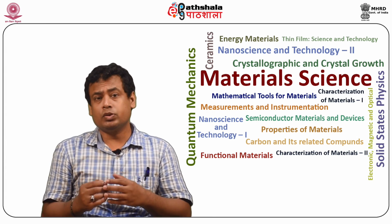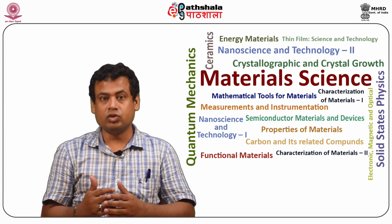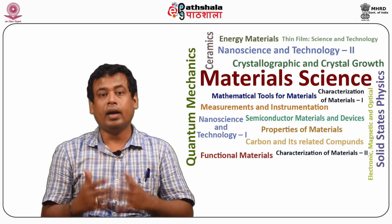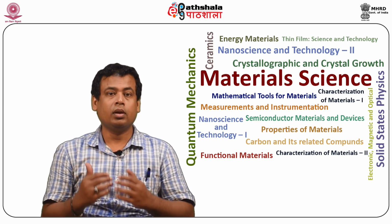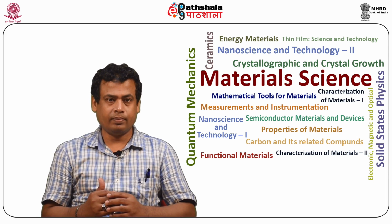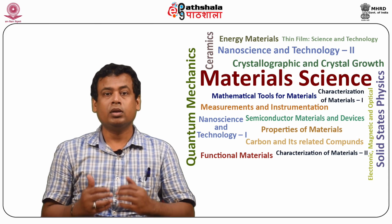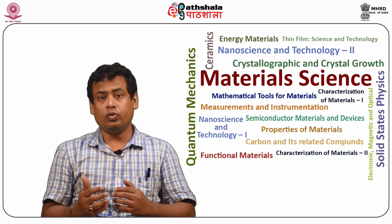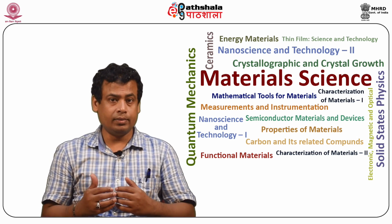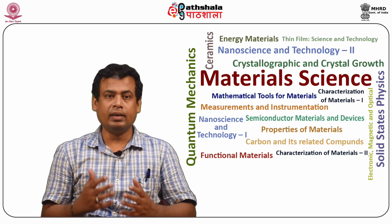So students, let us summarize what we have learned in this module. Electron beam lithography is used for writing arbitrary patterns on the resist with high resolution, high density, high sensitivity, and high reliability. These characteristics are interrelated to fabricate complex device structures at molecular level precision. Factors that complicate these objectives are delocalization of electrons due to forward and backscattering called proximity effects, collapse of the pattern due to swelling and capillary forces, and fluctuations in the sizes of features, line edges and roughnesses.